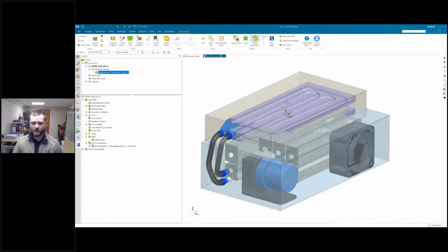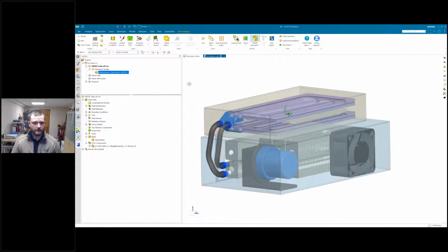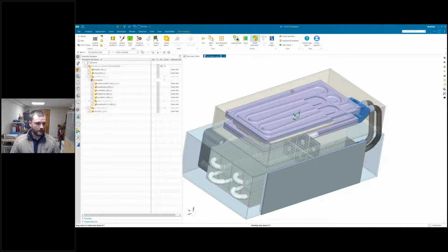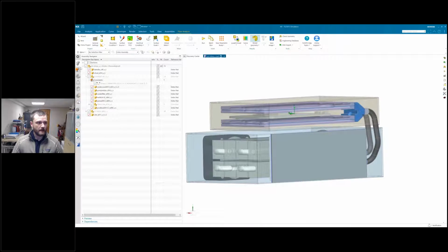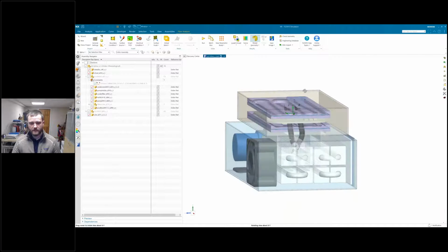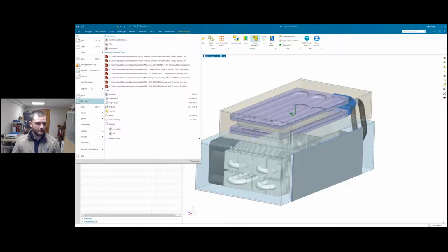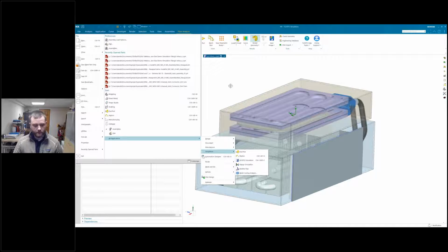But here we are. We have our model in CAD here in the NX environment. Here you can see we have our overall assembly tree. We have all our constraints for this entire system. The NX CAD environment is completely seamless and integrated within the NX environment. And I am already in FlowEFD. It's easy to jump into FlowEFD by simply going to file, applications, and simulation, and we're already in FlowEFD, or we can just hit Control-Shift-F.